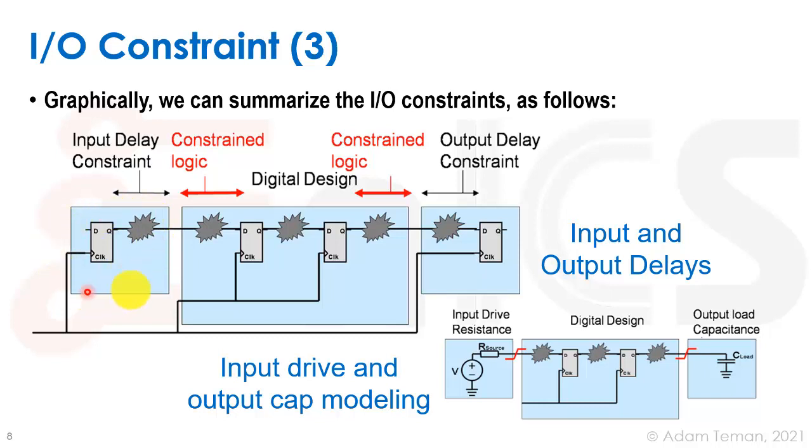But another thing is that even if this is a block that's being made in a certain specific chip and we're just hierarchically designing this, we are not in charge of this. We don't have it yet. It doesn't exist, and we have to model it. We'll see that there are ways to model it with interface logic modules that give us a better hierarchical approach when we're doing this inside a certain chip. But in any case, we need to model these outside parts in order to run our static timing analysis.